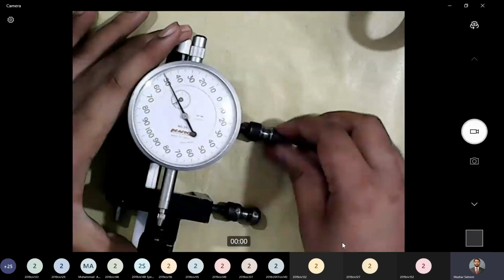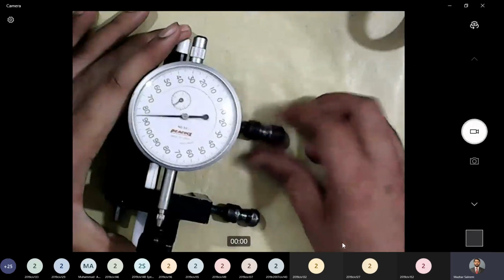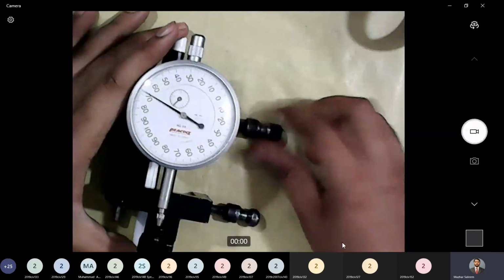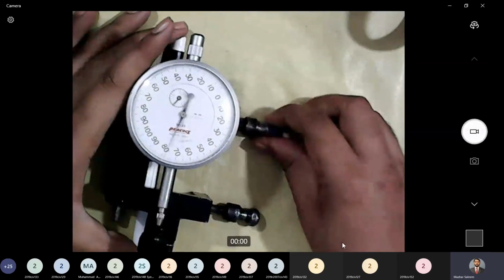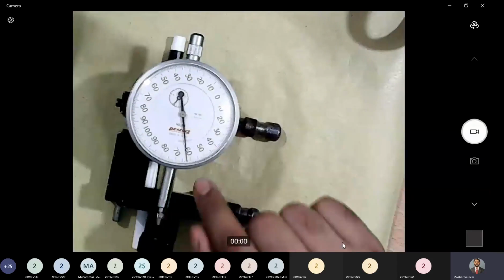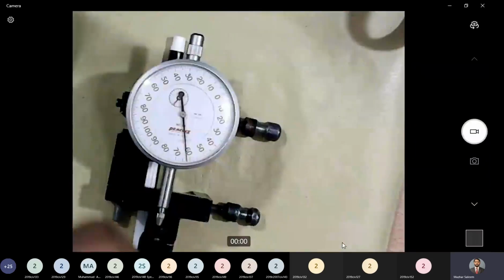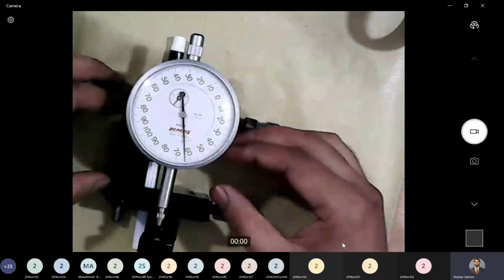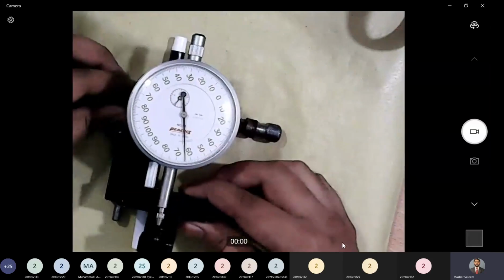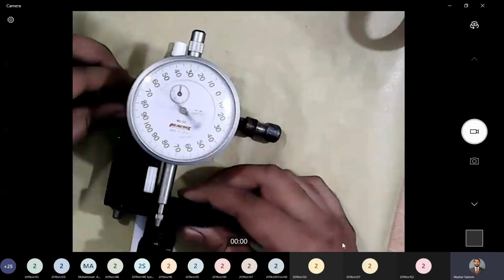These two components. We will clamp the steel bar, or in other words, we will clamp this extensometer on the steel bar. And when we apply, let's say, tensile load, we try to elongate the steel bar. This extensometer will open like this. You see, as I move these black components, just look at this component.